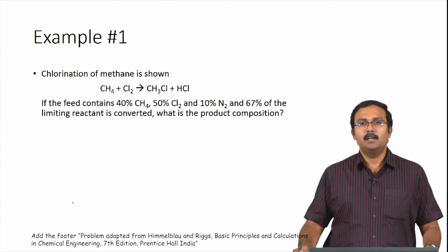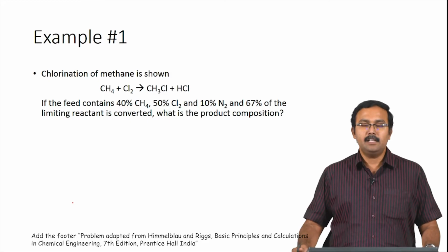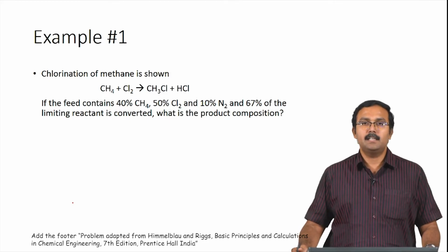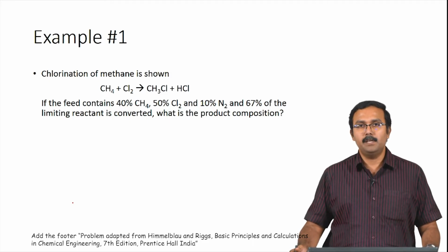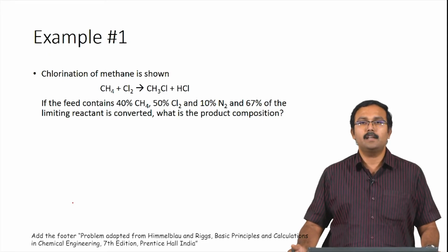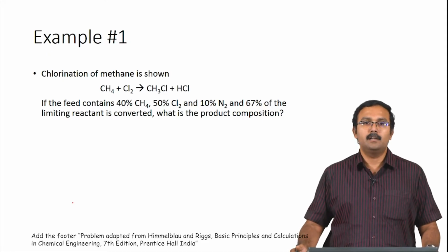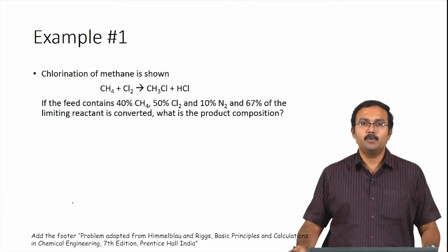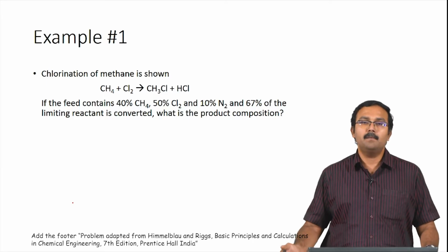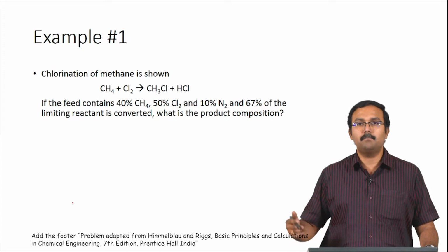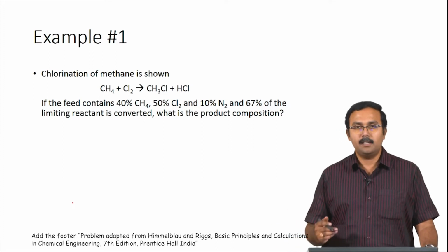If you remember, I had mentioned in one of the earlier lectures that in general mass percentages are used for solids and liquids and mole percentages are used for gases. So, here the composition which is given is for a gas, which would mean the percentages that have been given are for mole percentages, and thereby we use 100 moles as the basis instead of using a mass based basis. So, let us start solving this problem.